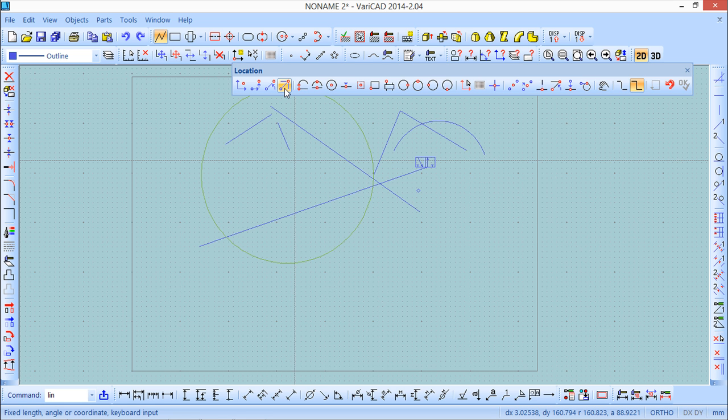done by the keyboard, or I like to call them absolute or incremental coordinates or polar coordinates, whatever you want. There are other names in other software. So the first concept you need to understand on this is that we work with coordinates, and if we don't give any other information, we are working with absolute coordinates, and the coordinate system, the world coordinate system of the VariCAD is here. Okay, if you go and approximate the entities of this point, it should give you 0, 0.